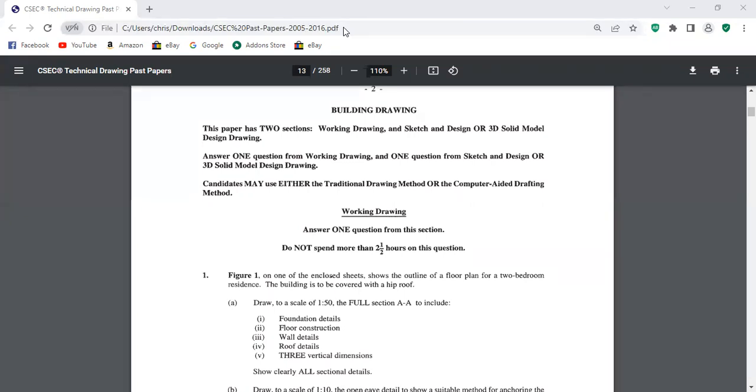kitchen, we first will establish our walls. So we'll start by drawing our first vertical wall. We then establish an elevation. From that, we establish our ring beam height, depth of foundation. So from the inside of this wall, we would offset from that wall to give the distance for the other wall in this case.